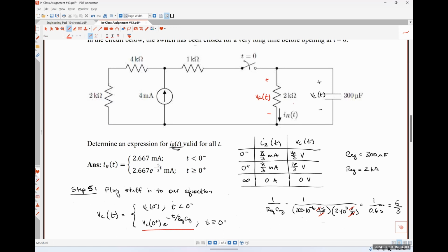because of Kirchhoff's voltage law. We know that the resistor current is an exponentially decaying signal, and it's exponentially decaying at the exact same rate as our capacitor voltage was because we just did that with Ohm's law. What do you think is going to be going on with the capacitor current?